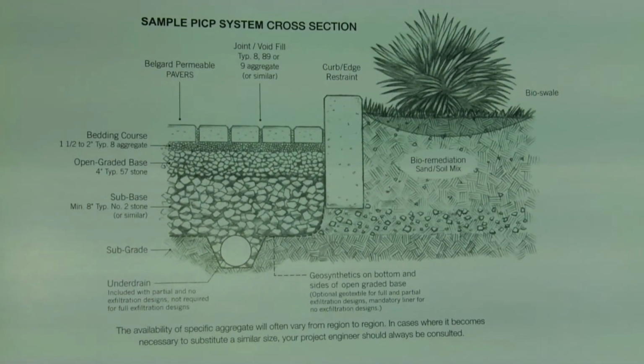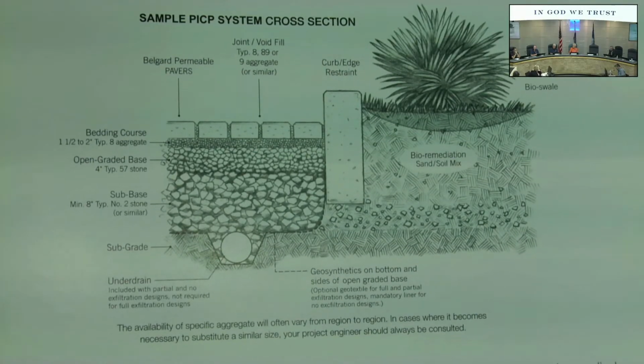Typically, yes. The crushed aggregate, what we see is they use a crushed granite, which actually becomes impervious after they compact it. So something a little bit larger stone to allow infiltration. But you're basically still using it as a leveling course to put your pavers on, because you can't obviously level the pavers on 57 stone. Right.